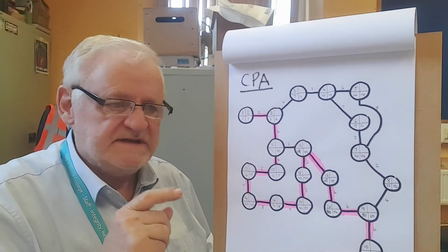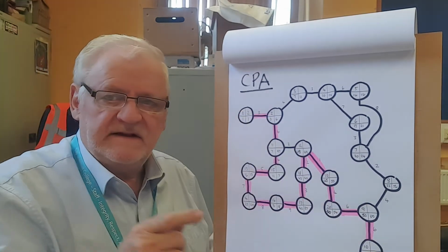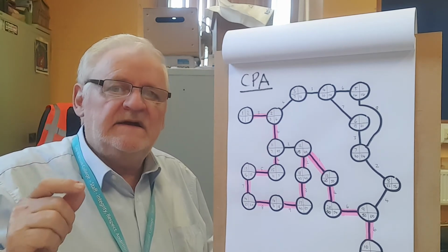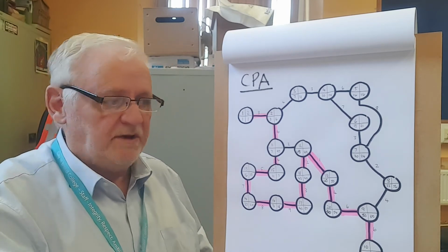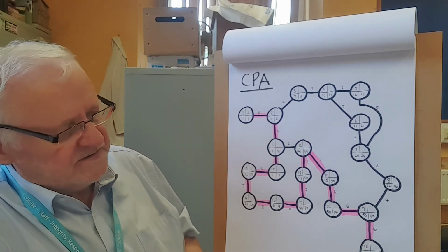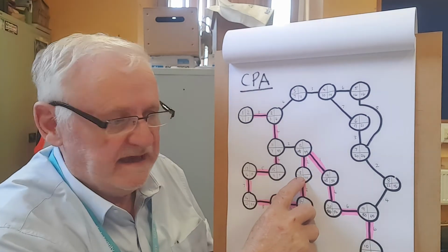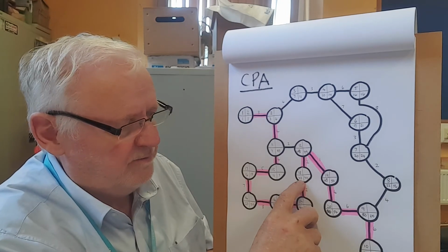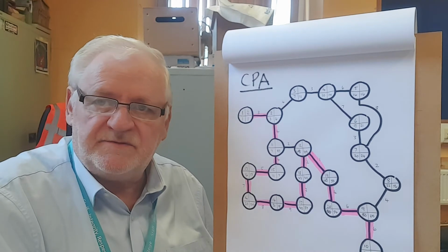You'll also notice that there's a pink line which goes right round like that. Now that pink line is the critical path. Okay, that's the path that's important to keep a very careful eye on, because you'll notice here that on event number 18 or day number 18, the earliest time that you can get to this particular stage would be day 43.